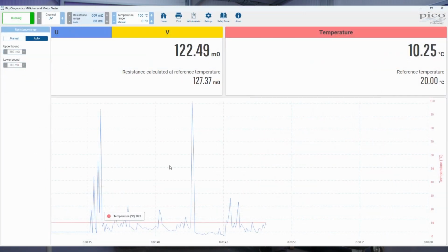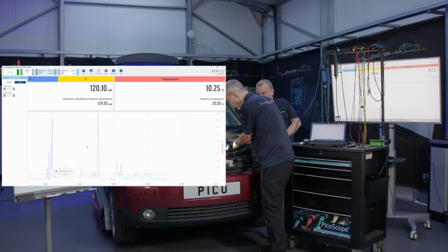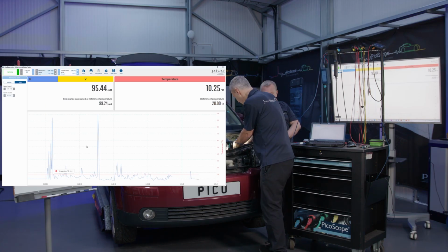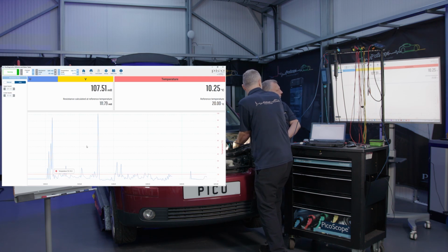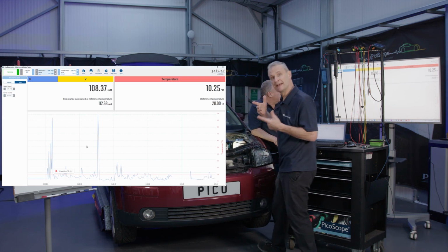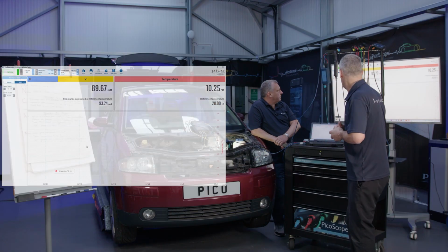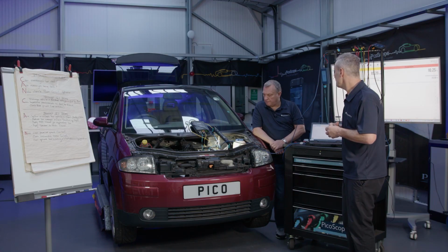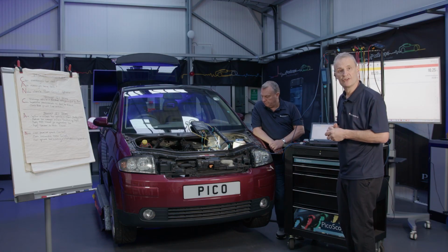So moving the wiring harness here, let's tug through here. I think we're fairly stable at that. I'll move it across now to the other side. So we've got 2 earth cables on the ABS ECU. And the opposite one again. Well, as you'd expect, they're both taking the same route in the harness and terminating at the same point. So on that, I think I'm happy to move forward that we have sufficient ground at this stage, yeah, with the load that we can apply. Yeah. Yeah, we can move on to the next step.